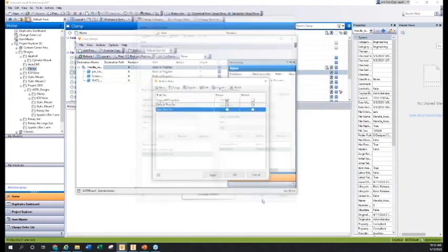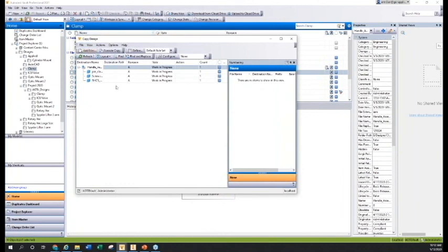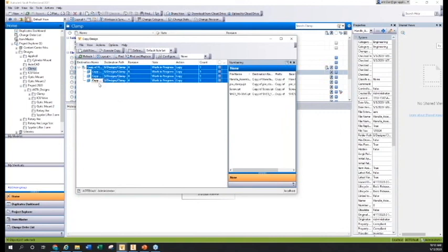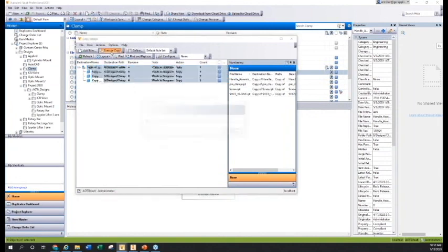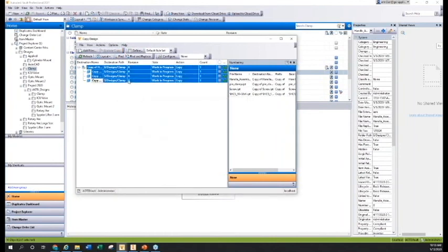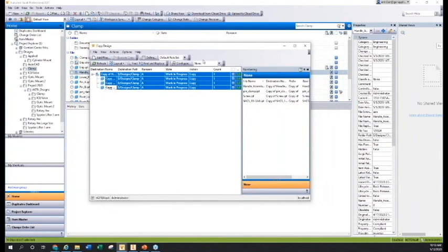So that's the process of creating that, and then we can add other files here. Eventually we'd change these names to something else. If you use the copy design, let's copy all of those. My default is to just add a copy in front of the name, but obviously you can use part numbering schemes, and eventually we execute the copy. We can copy to different folders as well. There's a lot of functionality here, and if you're using Vault Basic, this probably looks a bit different to you, because there are so many extra tools on the professional side with copy design.